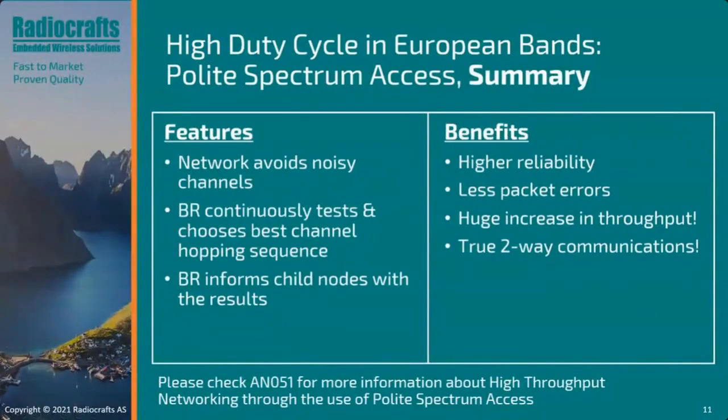So obviously this brings many benefits, as increasing duty cycle by such a huge margin makes over-the-air updates easier, frequent transmissions easier, lamp status monitoring easier, and more efficient and faster. And of course, implementing such noise sensing techniques ensures that noisy channels are avoided, which significantly reduces packet error rates and allows for more range per hop, so more range in general.